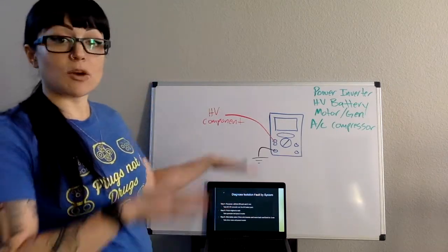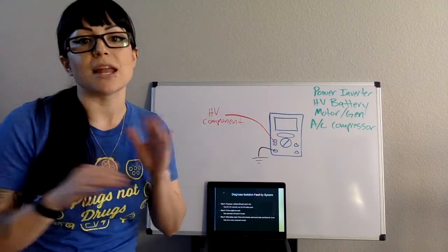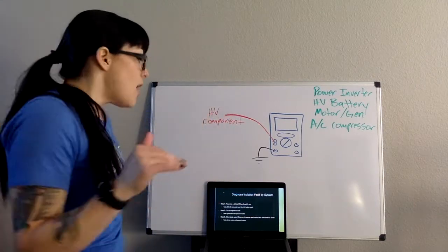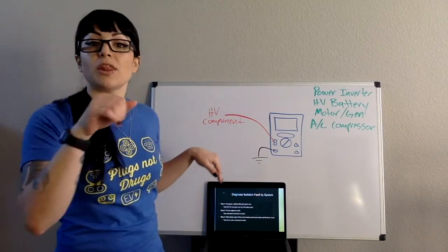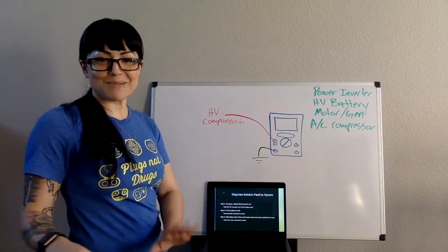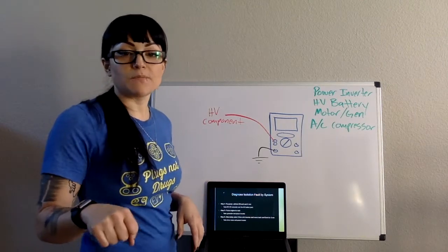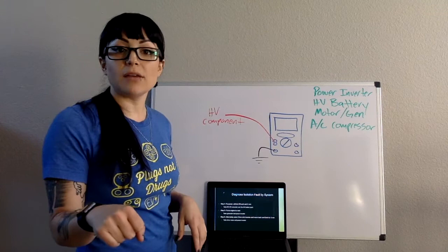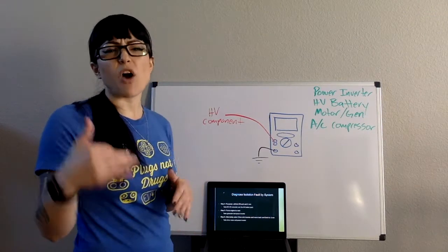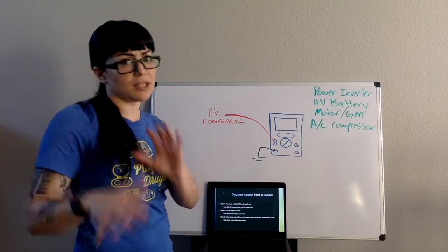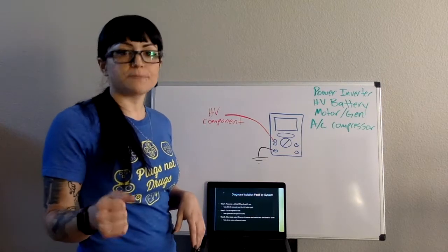Step 6. If I ran the engine for 2 minutes and no MIL is still on, the next step would be to take, obviously with your foot on the brake, your shifter and shift it either into drive or reverse, and you're going to alternate that. It doesn't have to be at a particular speed, but throw it in drive.